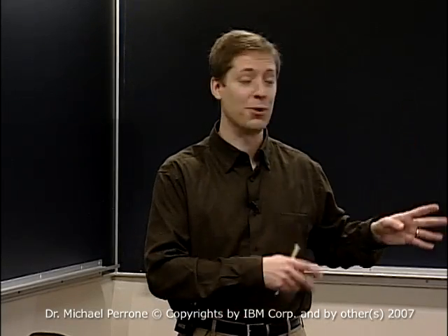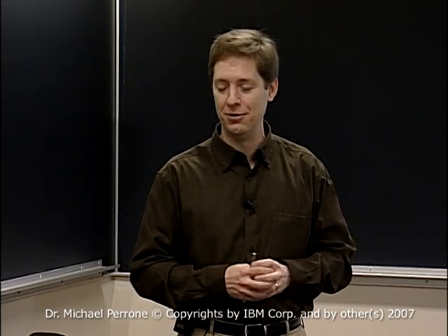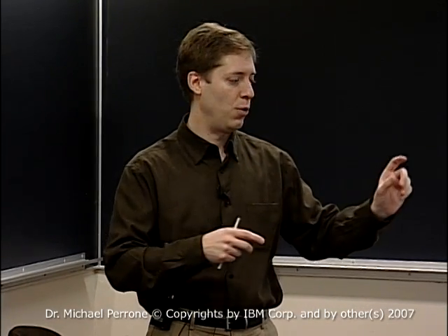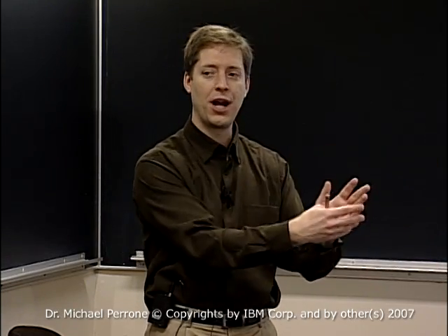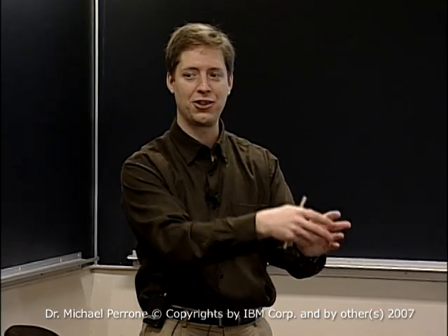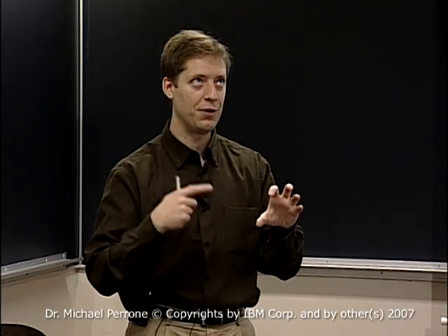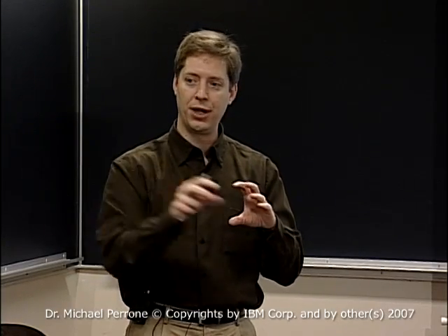So there are two ways. In research, we came up with an overlay mechanism. This is what people used to do 20 years ago, when processors were simple. Well, these processors are simple, so going back to the old technologies is actually a good thing to do. We had a video processing algorithm where we took video images, decoded them with one SPE, did some background subtraction with the next SPE, and some edge detection, and so each SPE was doing a different thing. But even then, the chunks of code were large, and we were spending 27% of the time swapping code out and bringing in new code.